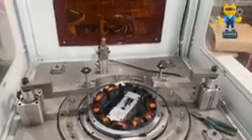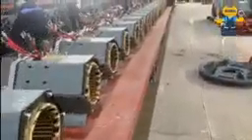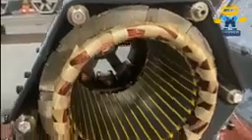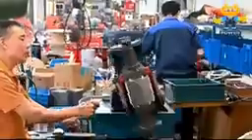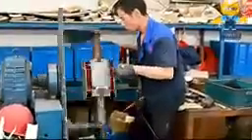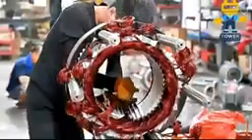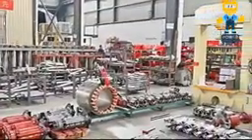The diesel engine is coupled with the alternator, and the diesel engine only produces the mechanical power. It gives this mechanical power on its engine shaft, which has a flywheel, and the flywheel is coupled with the coupling plate of the alternator. So the main rotor of the alternator is coupled and rotates with the power of the engine. The alternator has several parts, so I will explain these parts.